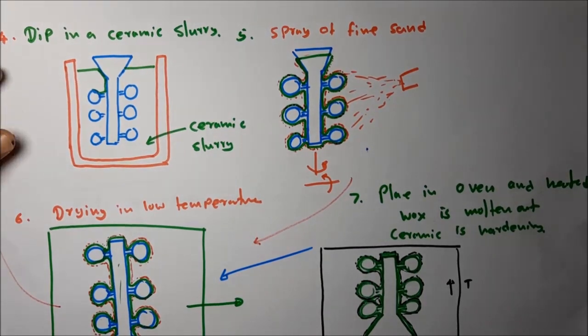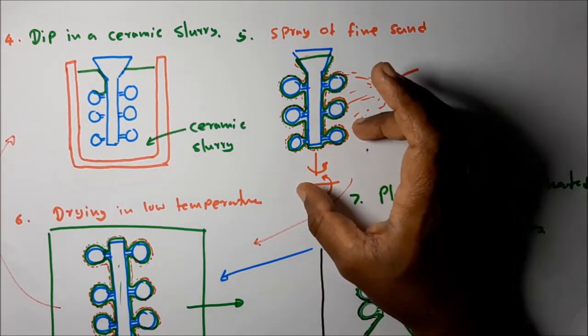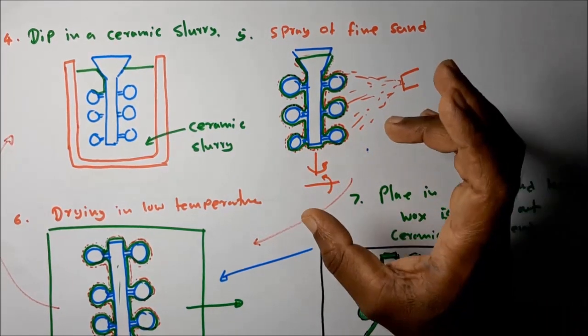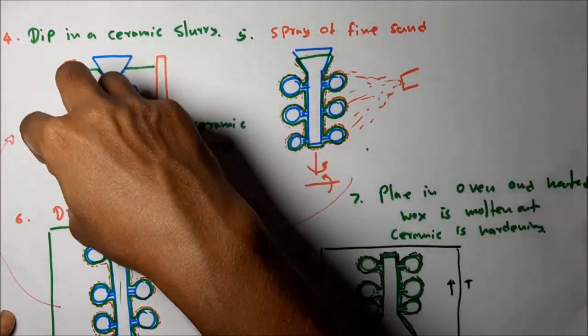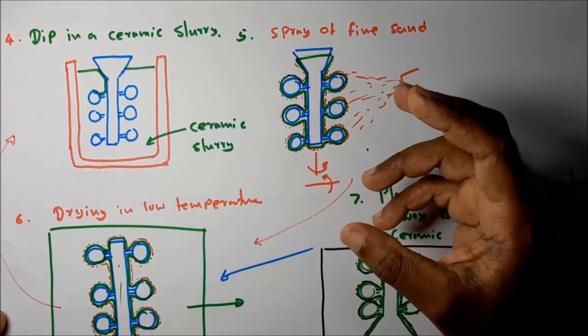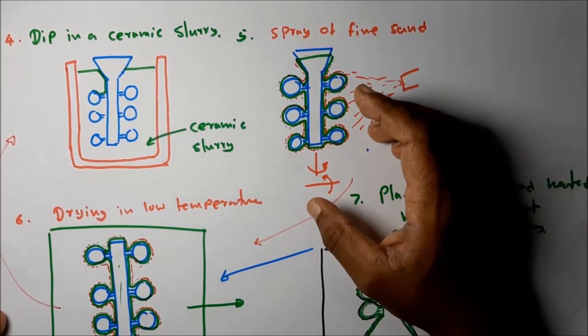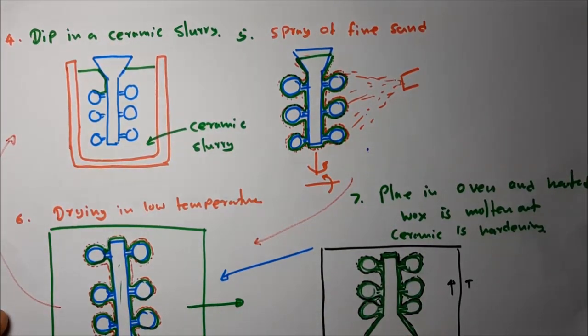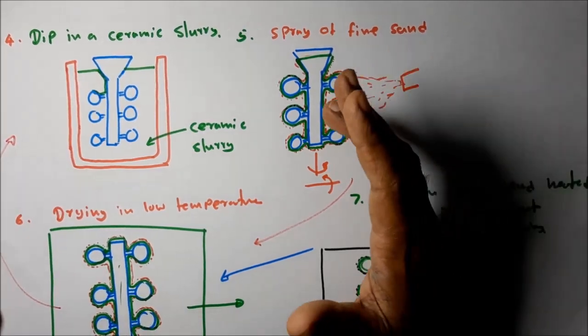So very high technology is needed for this operation, so this operation is only suitable for specific products, and also only suitable for mass production, and also it is limited to smaller products. If we take a very large product, it cannot be manufactured in this process because of the practical limitations of the process. Think about how large products are manufactured. It's a difficult process. This process is only suitable for products of a few kilograms, relatively smaller products, and also the surface finish is excellent. Dimensional accuracy is also very high. So this manufacturing method is suitable for mass production only.